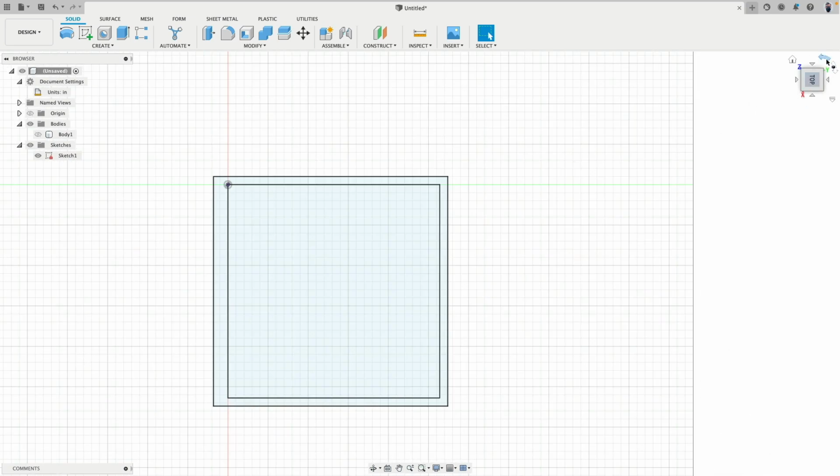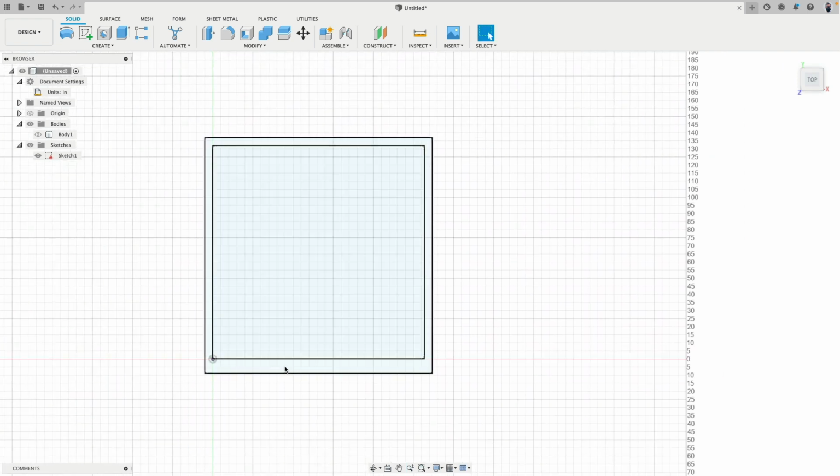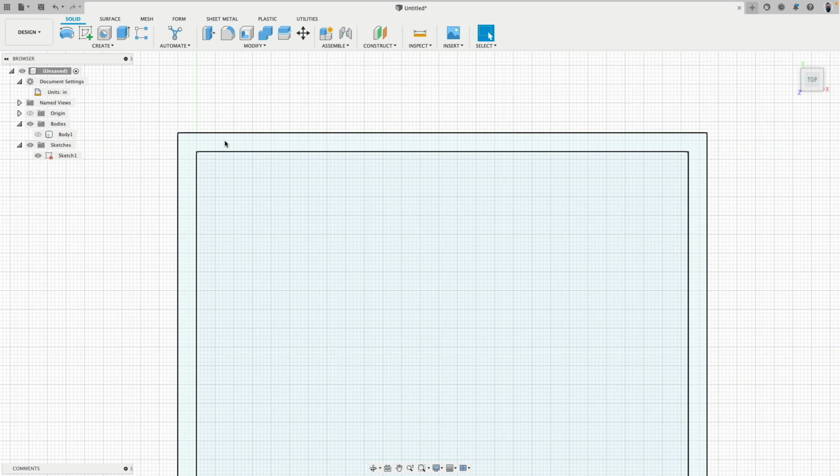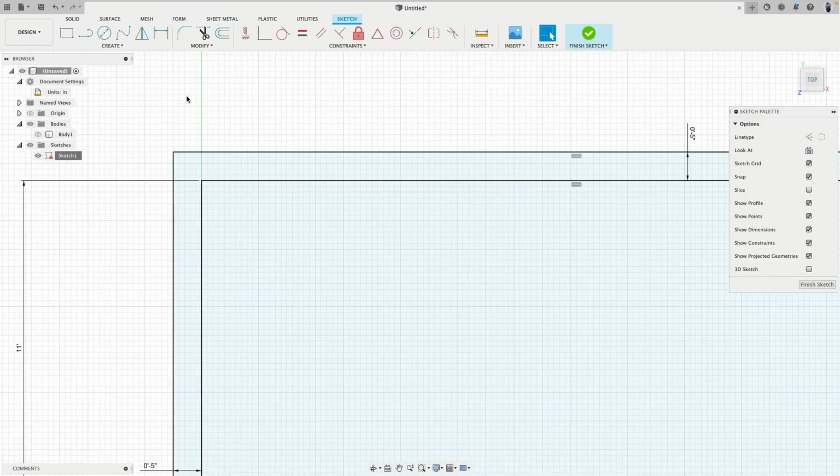Let's go back to top view, and there. So when this is the exterior wall, there is actually right here a door, and here's a window. The door is very easy to do. You saw that I extruded first the wall. Now right click, edit sketch. I will go back and edit actually everything for the door. Just the opening.